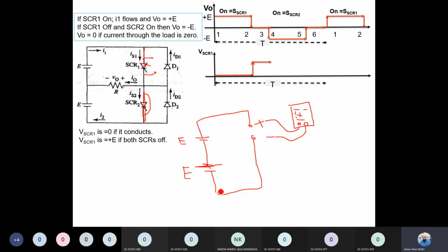ओके, the question may be कि ये दोनों ऐड होंगे या सब्ट्रैक्ट होंगे। These both 100 volt will make 200 volt. Why? Because the supply is connected in series. ये जो connected है इस सीरीज में, कैसे कनेक्टेड है, माइनस प्लस से दूसरी बैटरी के माइनस को कनेक्ट कर दिया गया है और then प्लस। तो माइनस प्लस, so all these are in series, ठीक है। तो जब सीरीज में होंगे तो आउटपुट वोल्टेज will be 2E, आउटपुट वोल्टेज आपको 2E हो जाएगा। Let's see what happens.